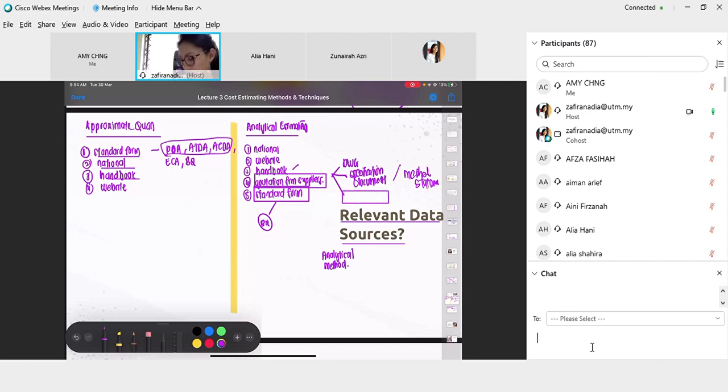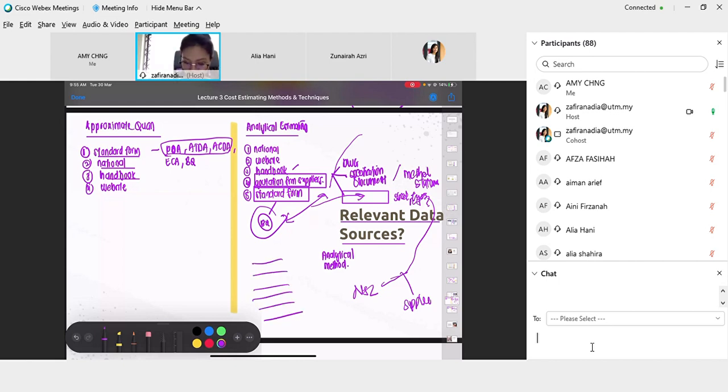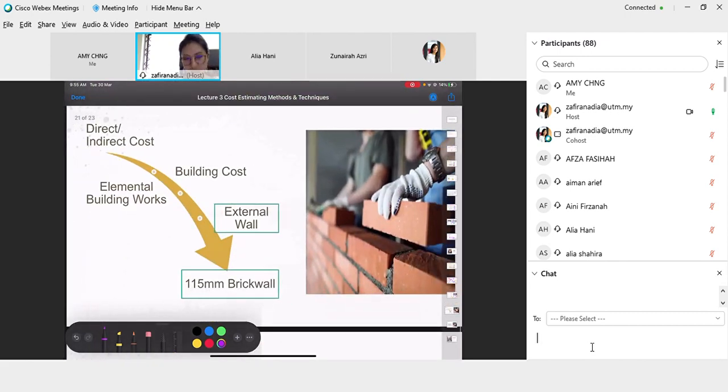For building a steel truss roof, let's say, how much? So you send it to APEC, or Haji, whatever, Haji or any uncle, and ask them to price. Those who price can be your NSC, nominated subcontractor, or your supplier. They will price and tell you. Then you double check against the BQ price, and then you put into the bill up rate what the price is. Okay?